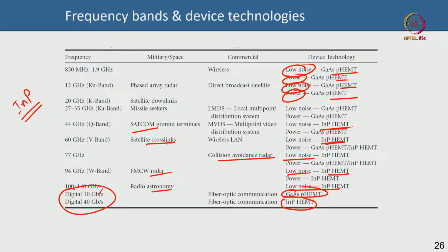So, people are smart. What people thought is, on a gallium arsenide substrate, can I enable an InGaAs channel with higher indium content, say 40% indium? Then it solves the purpose. But then the question is that if you grow such high indium content InGaAs, it will relax, correct? It cannot accommodate the strain to gallium arsenide.